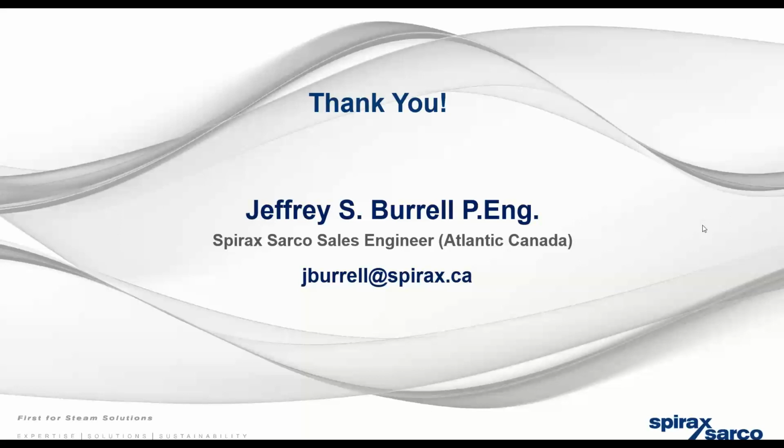If you use steel components, you might have to go around and tap them with a hammer to get them broken free for the winter. But yes, you can use a spring check valve as long as it has a very, very low cracking pressure.